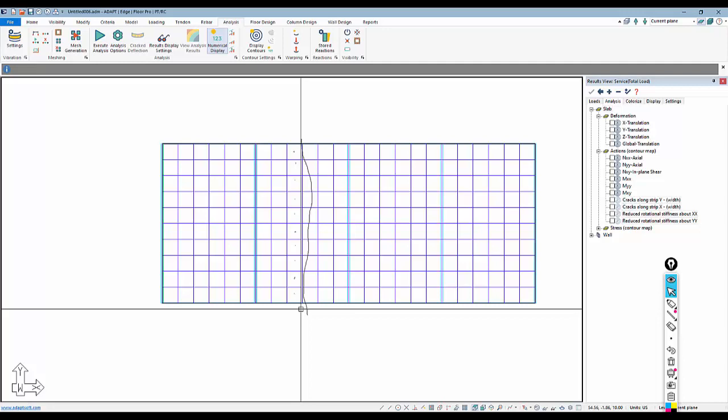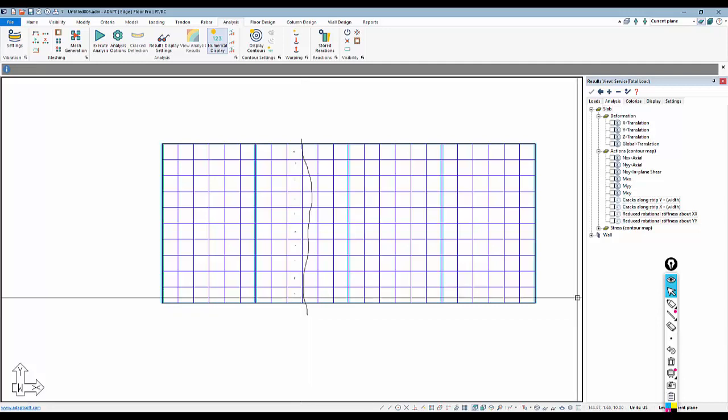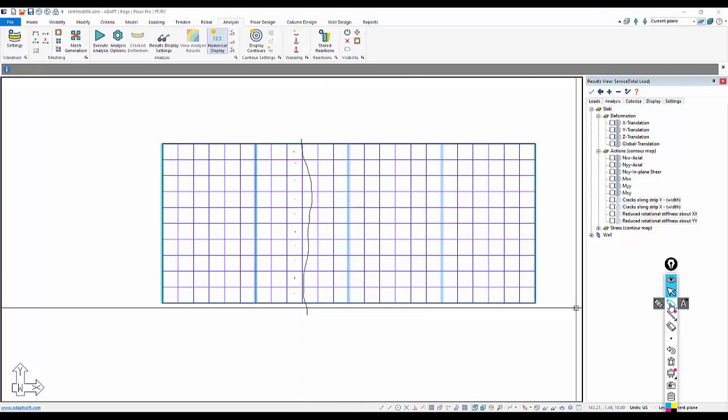In other cases, you may be required to actually create multiple slab regions in order to simulate a straight line. So I could have also, for example, created a slab edge here, and put the edge of the slab where I want the joint, and then I would create a second slab region. So we'd have 2 slab regions, 1 and 2, and that would be our joint, and then the program would mesh along that edge very cleanly, and you could go in and release the shells.